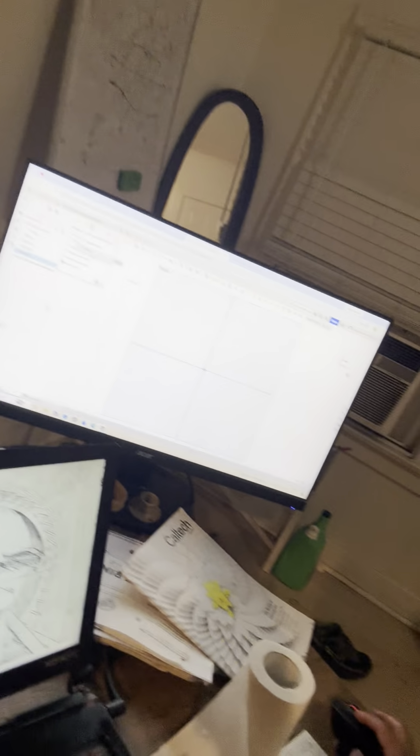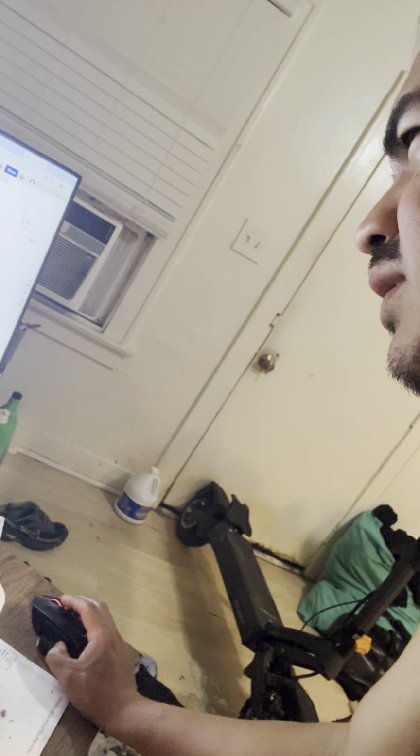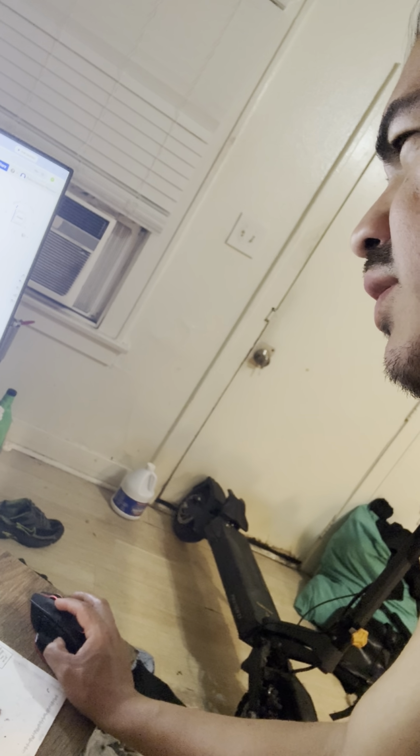Sketch, front, then it gives you center point circle, 3-point circle, or ellipse. We're just gonna keep it simple for today. So we go to center point circle, and we don't want to do a second one, clear selection, or just click escape.